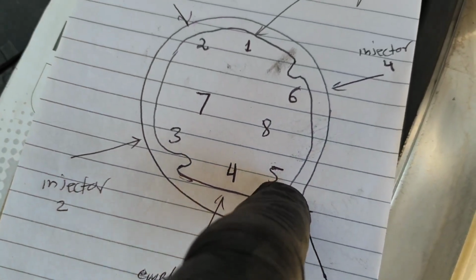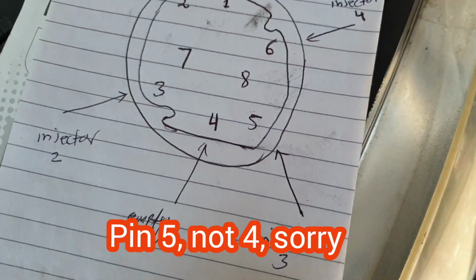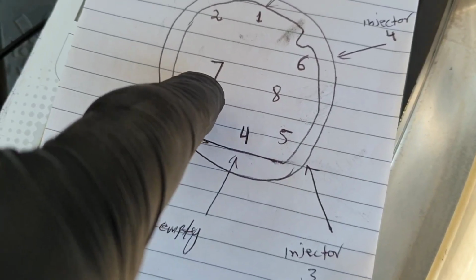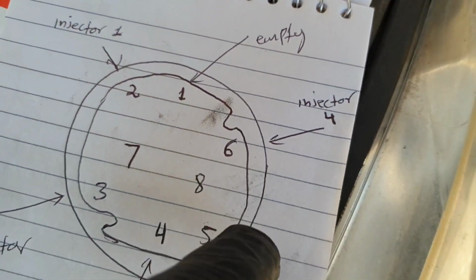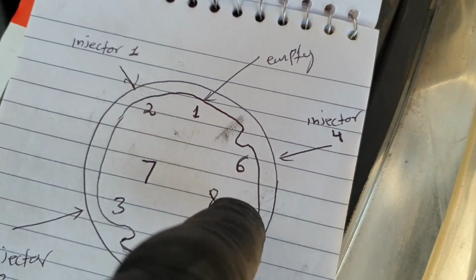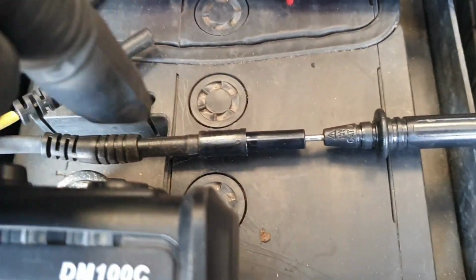Then the red lead of the multimeter goes on pin number 5 at the injector side or male side, and the black lead of the multimeter is going to be on pin 7. And to check the resistance of injector 4, the control wire or red lead of the multimeter should be connected to pin 6, and the black lead of the multimeter, as I have already connected, to pin 7.